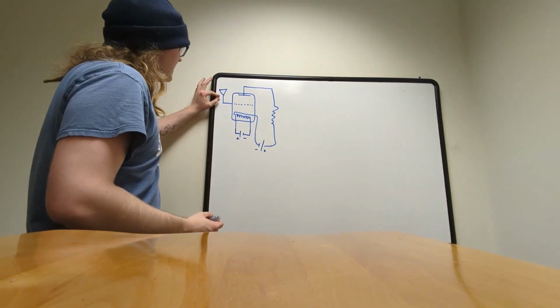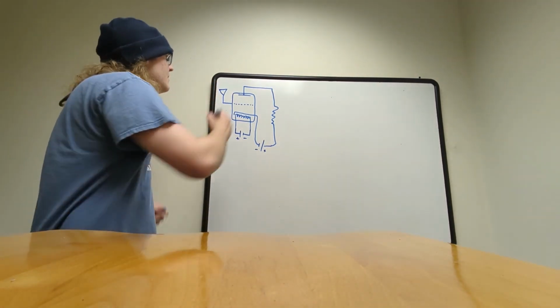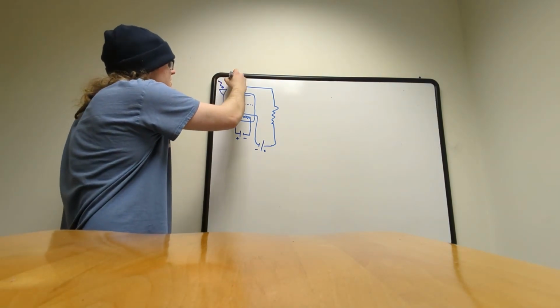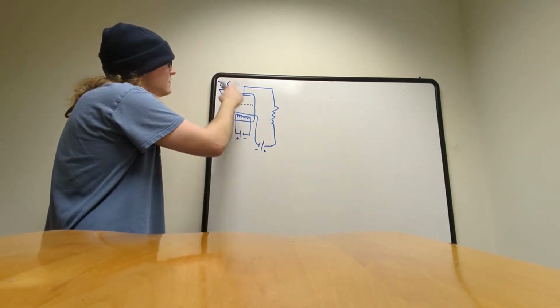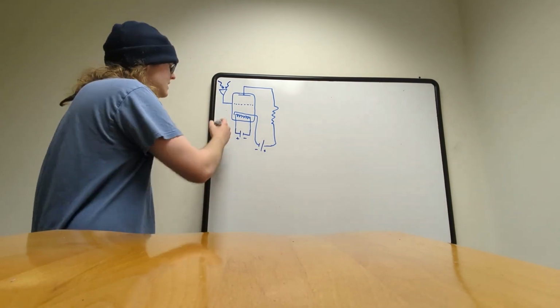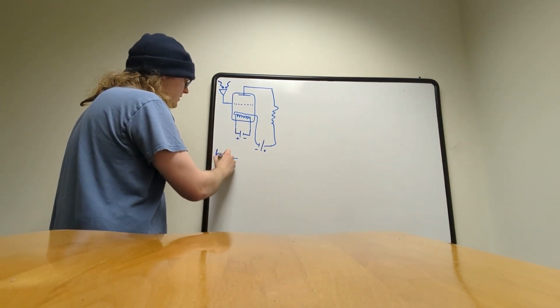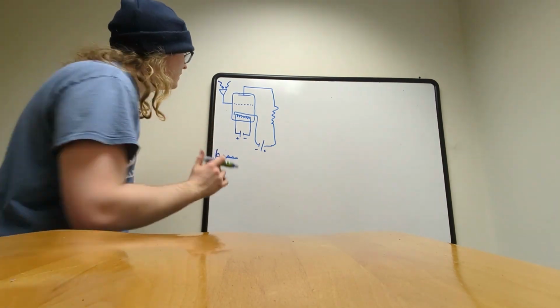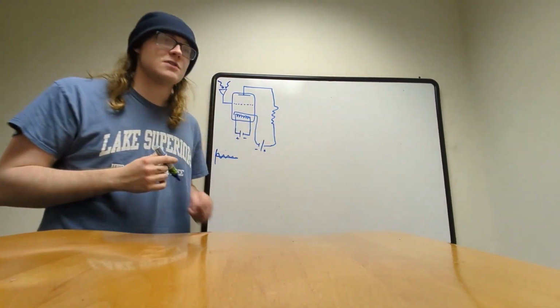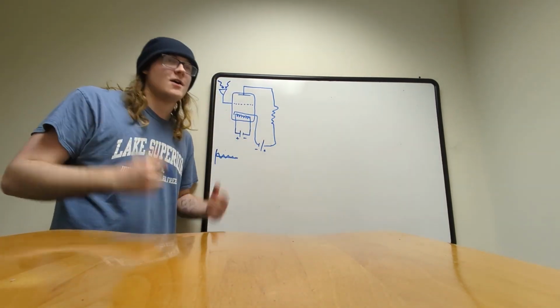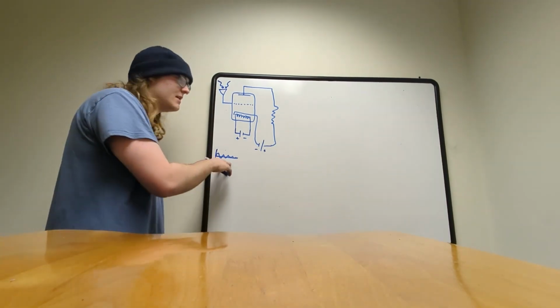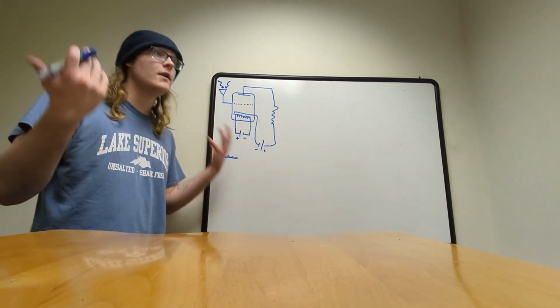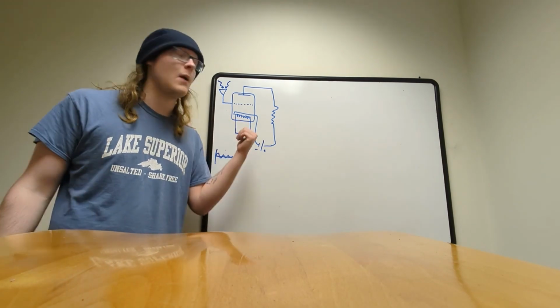Here we have an antenna that's connected to our grid, so imagine that as radio waves come in here, such as in a radio, a small positive voltage change will exist across this grid, something like this, or maybe some noise in between, but nonetheless it'll be very small. Now, if we try and hook this antenna into our circuit just directly, the noise across our speakers would be very, very low because the voltage across it is very small. What we want to do is amplify it, and vacuum tubes allow us to do this.